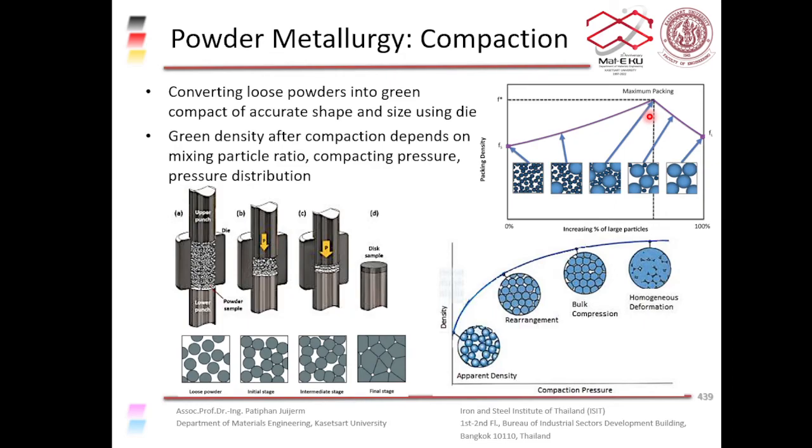But if you have just big chunks of rock, you have a lot of holes between those pieces of rocks. So you need sand, which is a fine aggregate, to go in and fill in the holes between the big chunks of rocks as well. So it is the same concept. If you mix two types of particles with different sizes, you would get higher density.